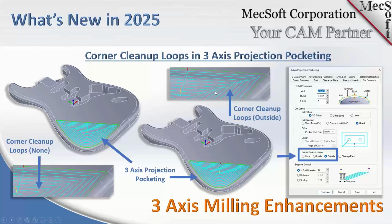So the loop is extended to the outside perimeter of the corner, which adds some cleanup right here in this pass, at the corner itself. But it also allows the tool to turn that corner without so much jerking motion on the CNC machine.